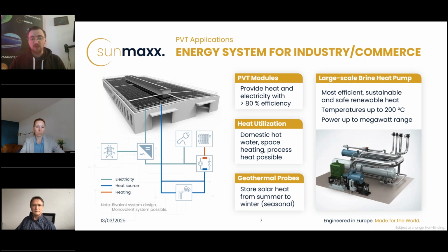And because we combine it, we have a positive effect in winter. So the brine heat pump can choose: do I choose the PVT plant on the roof as my source or the earth probe? And with that, we can reach very high efficiencies of the brine heat pump, and with that, of course, a very low electrical demand of the brine heat pump, and it is possible to scale up the PVT plant endlessly, let's say.